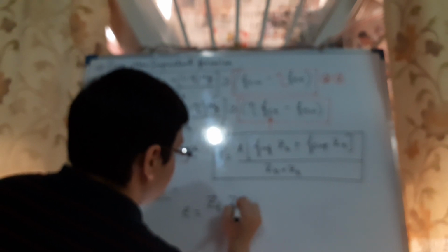Eccentricity. So what will be the eccentricity? This is again derived, e is equals to Zt Zb inside brackets F inferior minus F superior divided by A into F superior Zt plus F inferior Zb.